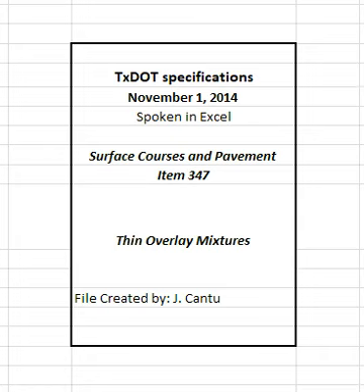2.3 Baghouse fines. Fines collected by the baghouse or other dust collecting equipment may be reintroduced into the mixing drum. 2.4 Asphalt binder. Furnish performance graded, PG, asphalt binder with a high temperature grade of PG 76 or 70 and a low temperature grade as shown on the plans, in accordance with Section 300.2.10, Performance Graded Binders.